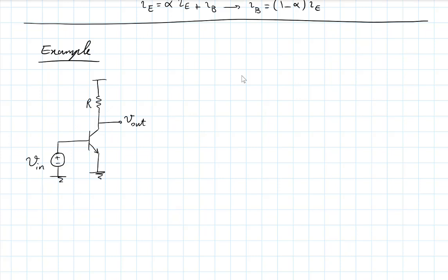Okay, we analyzed this briefly, and we realized that the big change in the output would happen when Vin is somewhere around 0.7. So when it goes from 0.5 to 0.6 to 0.7, gradually this input diode is turning on, and there is a large current in the collector that will then go through that resistor also and lead to a voltage drop at this node. And up here you had some constant voltage. Okay.